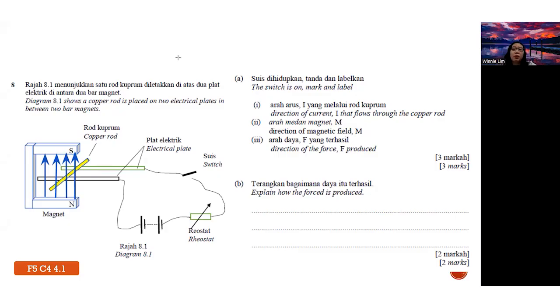The field on this current-carrying conductor, the yellow rod, is basically circular. So I sketch out the idea first. What happens is the blue field and the rod's field interact and combine and produce a catapult field. You can use Fleming's left-hand rule to determine the direction of the force produced.